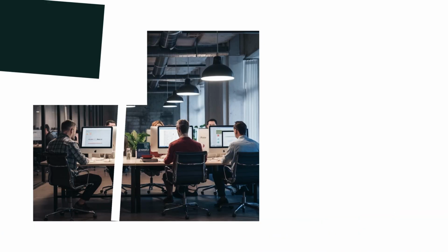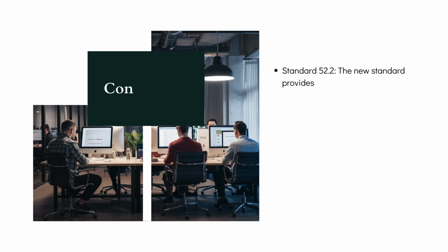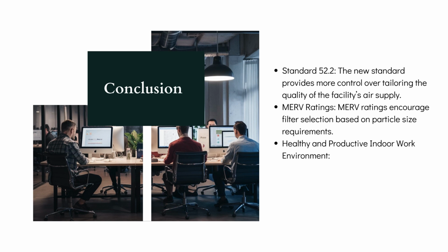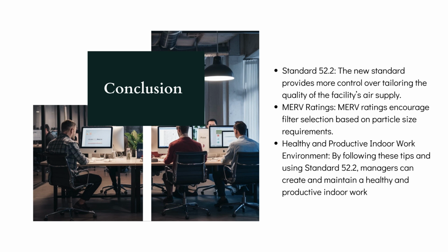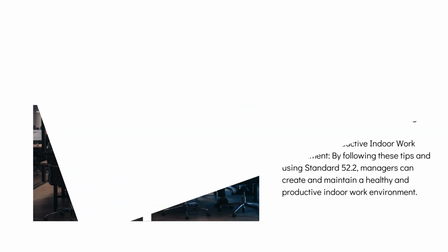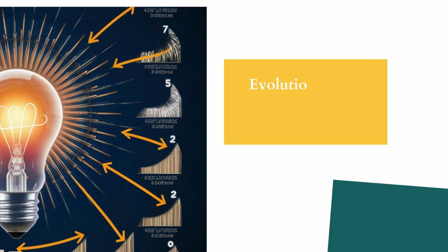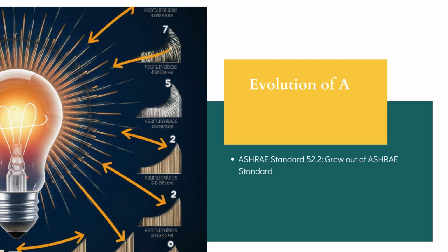As we transition to the new MERV ratings, here are some tips to keep in mind. Work with factory representatives to obtain documentation showing the new MERV ratings for existing products. Look for new MERV ratings that will appear along with the old dust spot or DOP rating on filters and filter packaging. Use these equivalencies to better understand the new ratings. Create a new strategy for evaluating filters in terms of target particle sizes. Inspect filter installations for good sealing and monitor filters regularly.